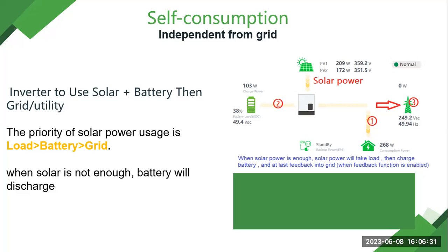When you get the inverter, you can see in our monitor system we can enable AC charge priority, forced discharge, and maybe peak shaving and a lot of settings. But if you want to use this, it is the default mode from our manufacturer. You do not need to change any settings.